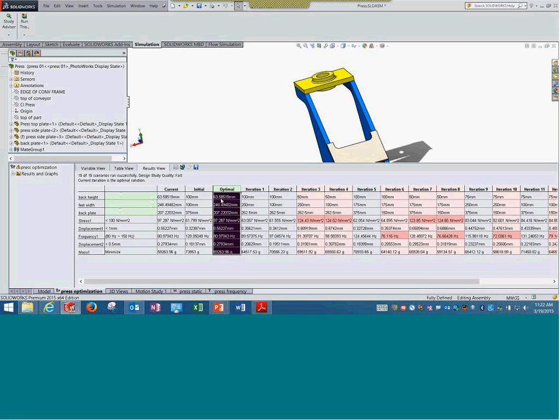So first, we can take these dimensions and then round them off. Typically, 63 might change to 65, 248 might change to 250, and those things can be changed appropriately as per practical requirements. And thereon, we might want to do one more analysis to check the dimensions. But this is a good indication of different dimensions that one can use to model, and you're concluding on the design without much brain from your end. We are just giving the limits, and the software can guide you on that.